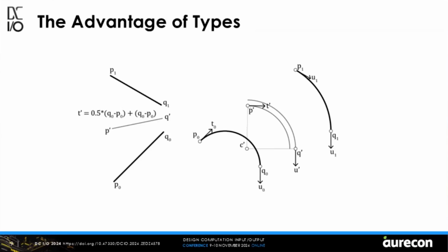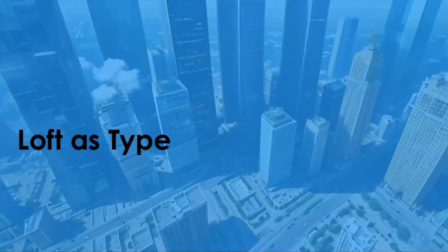This is super easy with a line because a line is just an interpolation of 2 points and you always get a line out. But when we attempt to do this with an arc, we get over-restrained and get an elliptical arc. A particular type of behavior, and thus esoteric type, for this industry would be a way of interpolating arcs such that we always get an arc back. The reason that this interpolation behavior is desirable within the AEC is that it makes a more desirable type of loft within its parameters, which would be primarily used for things like tunnels.